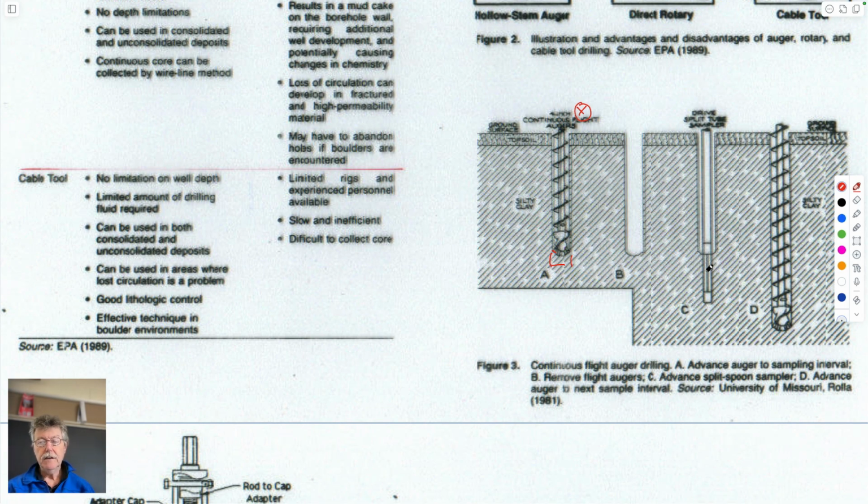They open, they have a cutting shoe at the base and a coupling onto drill steel up to the top, and you put it down to the bottom of your drill hole, and then you physically bang it into the ground with a monkey, it's called a monkey hammer, and it goes in. It takes a sample of the material that would have been here. And then when you pull this out of the hole, it recovers it to the surface. You break it off the end. You take the cutting shoe off. You take the disturbed sample out.